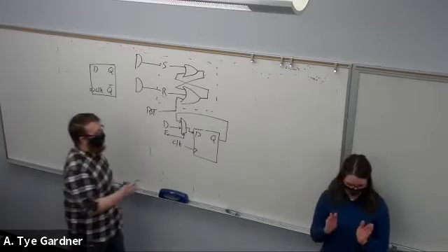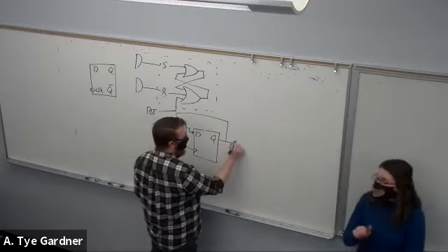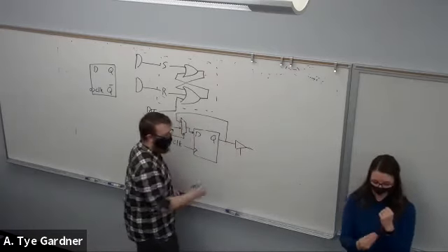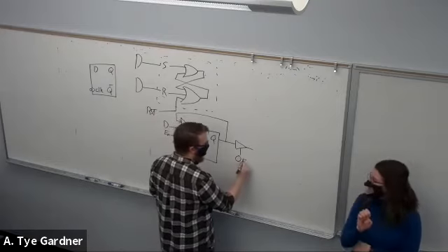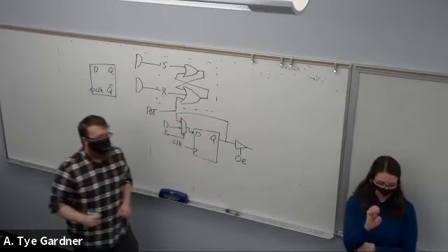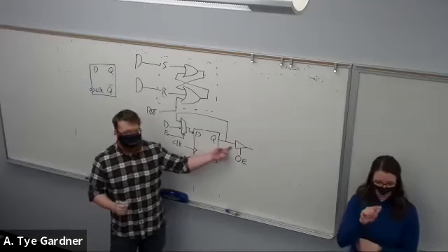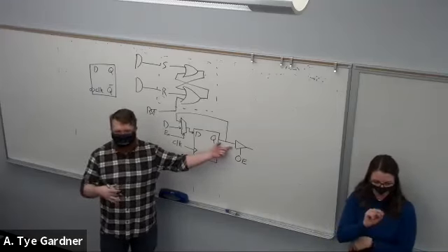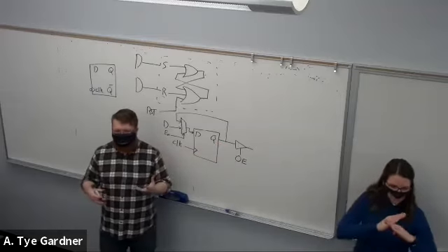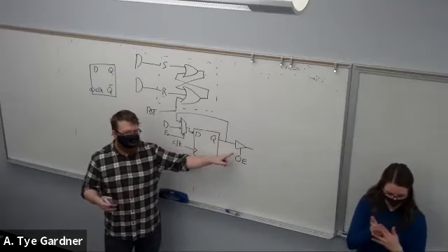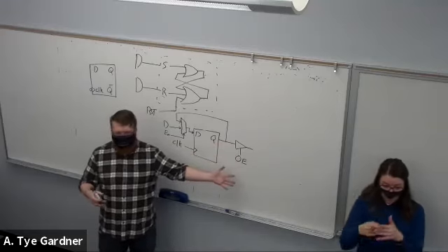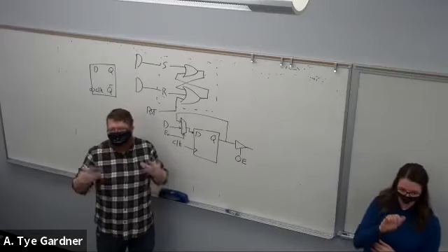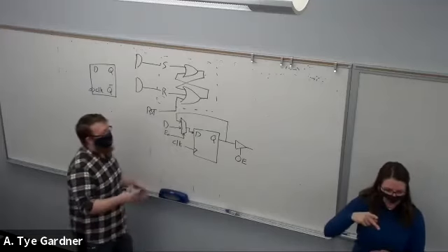One other thing that we can add onto this that we'll see coming up is an output enable that we usually label as OE. This is what we would call tri-state. It's a buffer, so it's like an inverter, but it doesn't invert. It just passes it through. If it is enabled, it passes the value through. If it's not enabled, it goes to high Z, high impedance. You'll hear both of those, meaning it just doesn't drive the signal. This is really useful